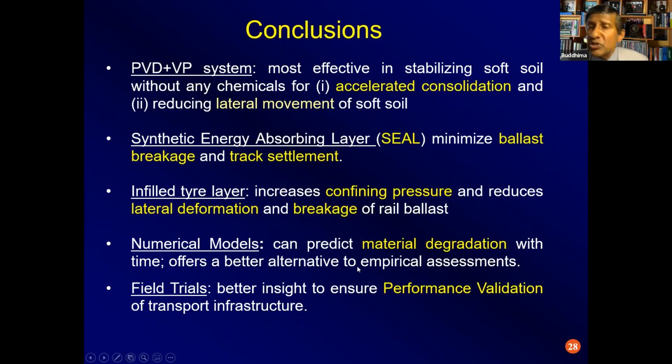The finite element models and distinct element models that I showed earlier are very useful to predict whether your soil can mud pump or fail in undrained instability, or whether the settlements can be too much. And these numerical models can now be used in conjunction with conventional design. Once the tracks are built, please don't forget to monitor them. So field instrumentation is very useful to make sure that your design does the work as you initially predicted or desired, by performance validation through full instrumentation.